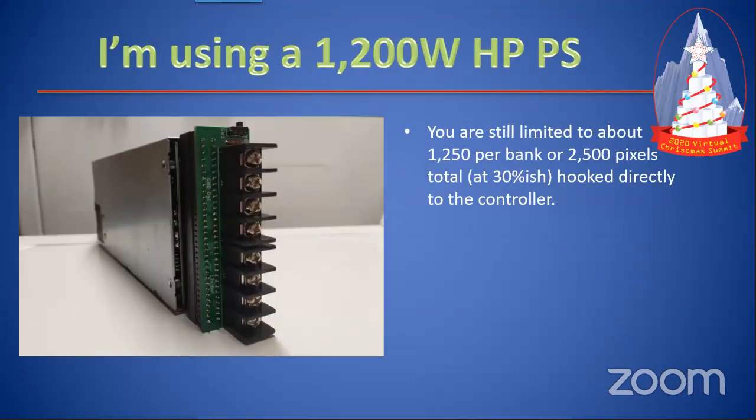Some may say, "I'm using a 1,200 watt power supply." You're still limited. And the reason is, again, it's back to the controller. You're not actually going to be able to utilize all of that potential power you have in that power supply when it's directly connected to the controller. And we're going to go through that.